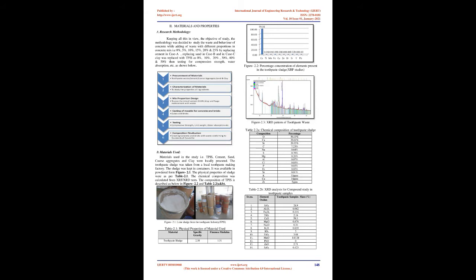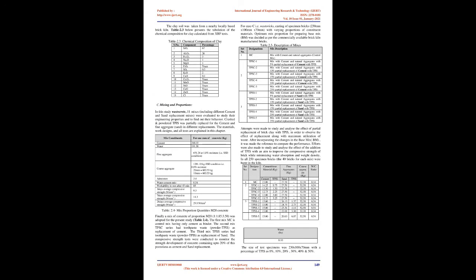Results show the satisfactory addition of as much as 20% sludge at 960 degrees Celsius to 1000 degrees Celsius, although the optimum addition is 10% sludge with 24% moisture content in a molded mix and firing temperature of 880 degrees Celsius to 960 degrees Celsius.